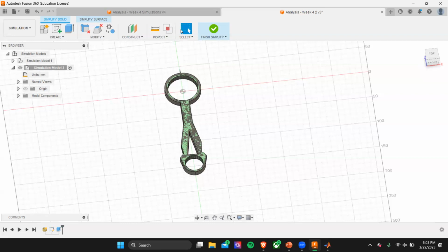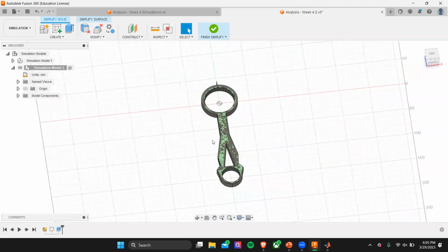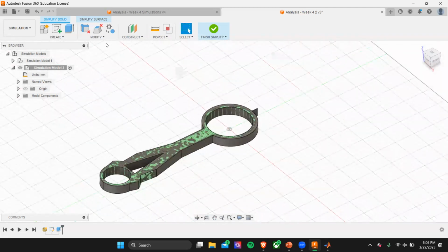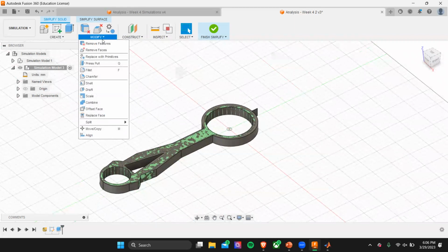Okay, I'm gonna keep going and then we'll go back and do the sketch in 1 second. So once you have that completed and your cut extrude done, you're gonna want to go into this modify right here. So like we talked about before, sharp faces actually cause a lot of issues when you're dealing with a kind of load applied to it.